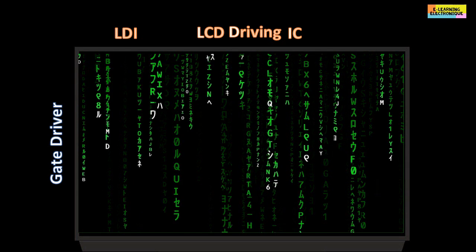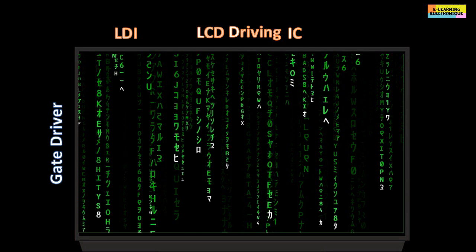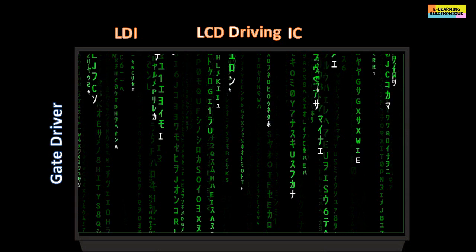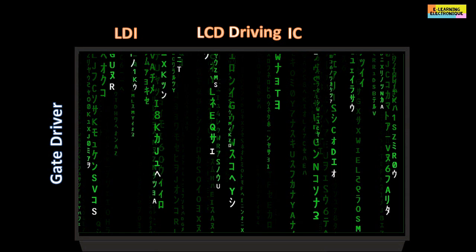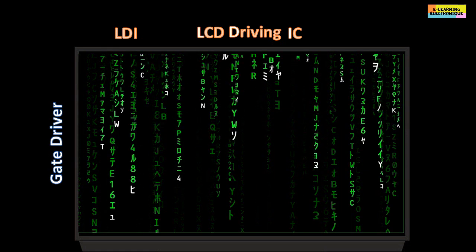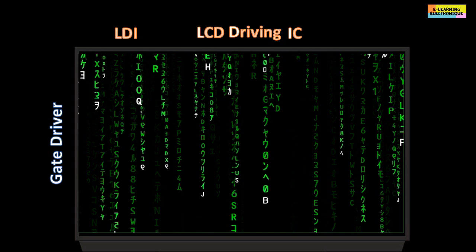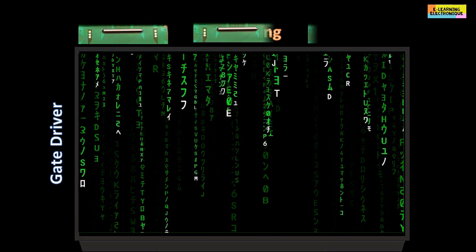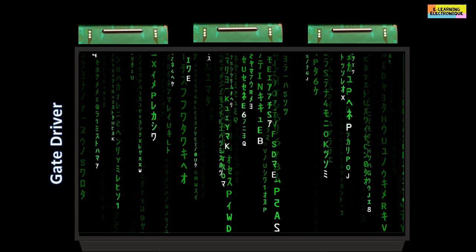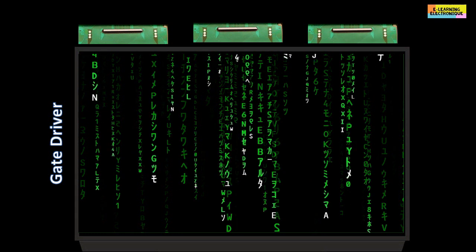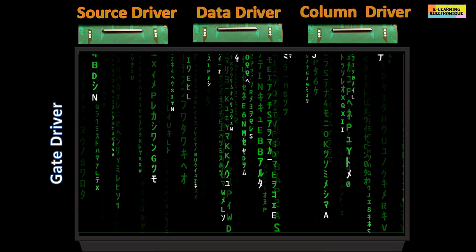This component controls in a horizontal way the supply of the TFT via their gate with VGH and VGL. For the image data, they are transmitted vertically to the source of TFT. The chips that control the data are located at the top or bottom of the screen. These chips have several names like source drivers, in reference to their connection to the sources of the TFT, data driver or column driver because of the vertical arrangement of this control resembling columns.